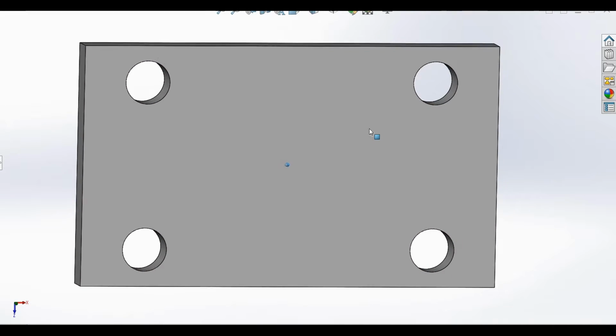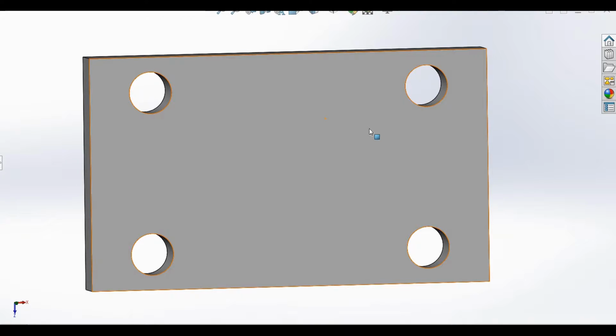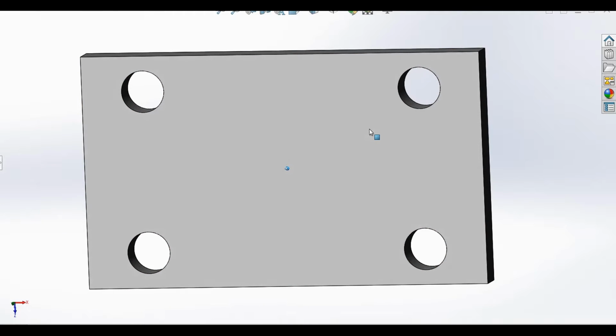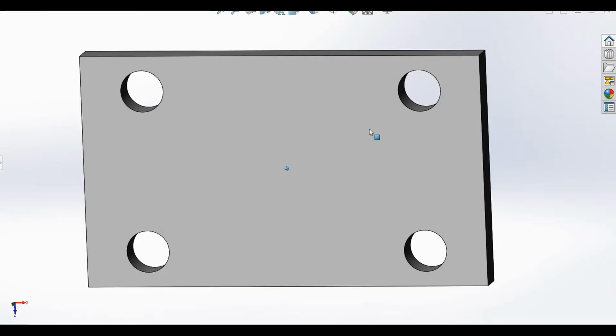So the way we get around this in manufacturing is we build in a little bit of wiggle room into the process so that the machinist has a certain amount of error that's allowed in order to make the part still usable but machinable in a reasonable amount of time with a reasonable amount of equipment.